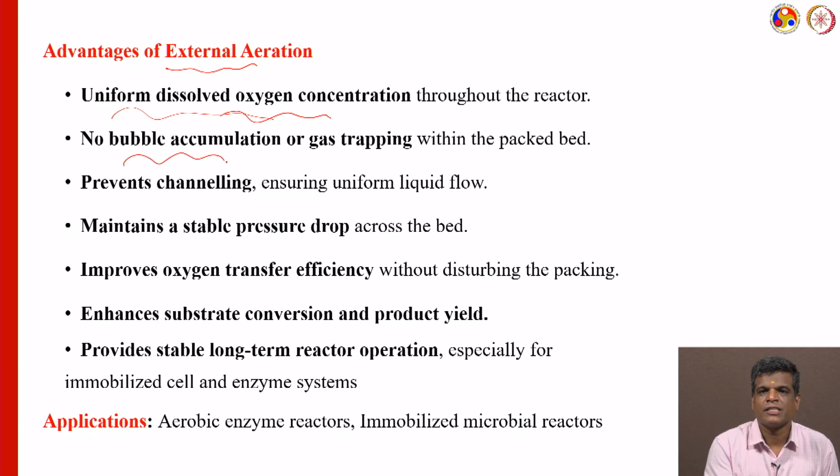No bubble accumulation or gas trapping within the packed bed here. Of course, external aeration prevents channeling and ensures uniform liquid flow throughout.